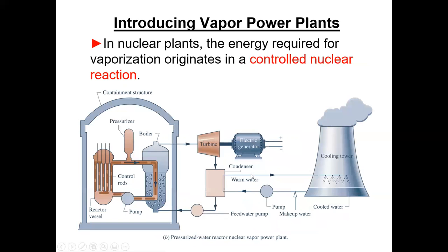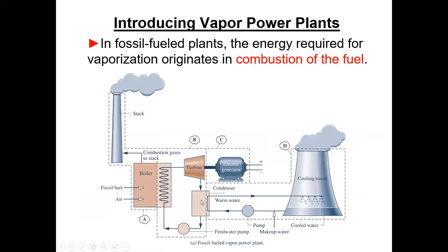And then we have the heat rejection portion of the cycle. So this is the condenser, and heat's rejected from there into, somehow we have to cool this. We have to condense this mostly vapor, very low pressure, low temperature vapor coming out of the turbine. And commonly we use lake water, river water from some large body that we can pump out, pump through here, fairly cool, take it back warmer, and go back to the lake, or this is showing the cooling temperature.